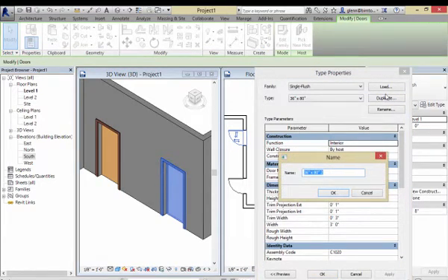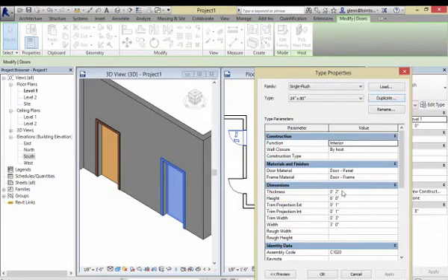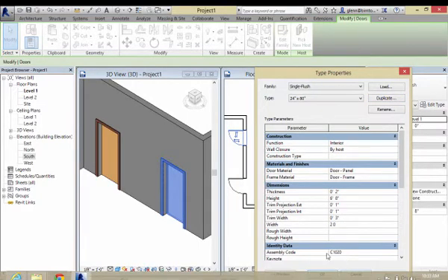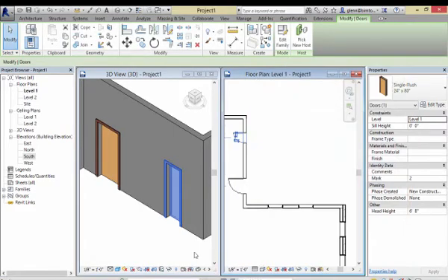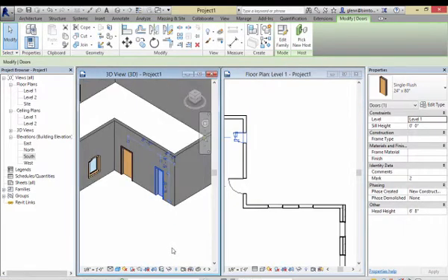And you're going to do this a lot through the quarter. Make a new type. Again, that's just a name. But then we go through and put in the size. Okay, so feel pretty good? Say OK, and I got a 24-inch door. And that's OK for changing sizes.